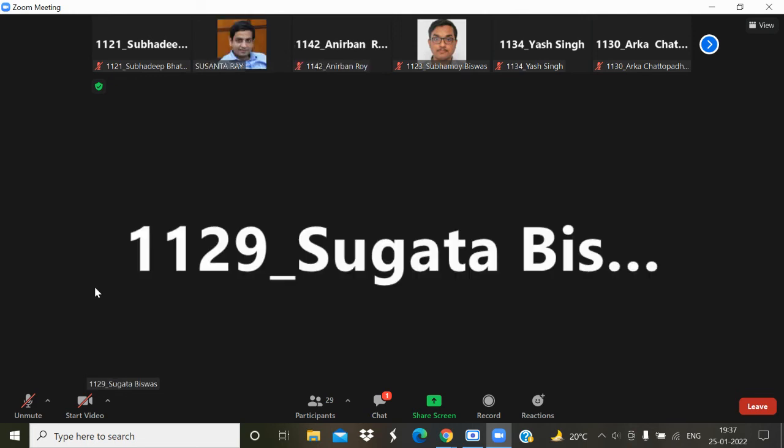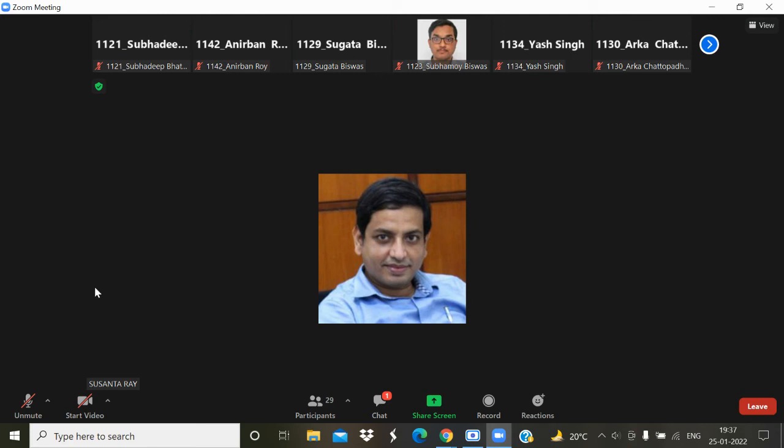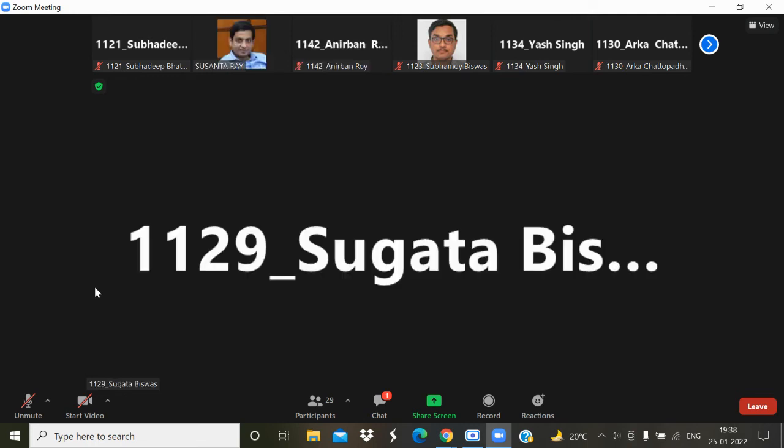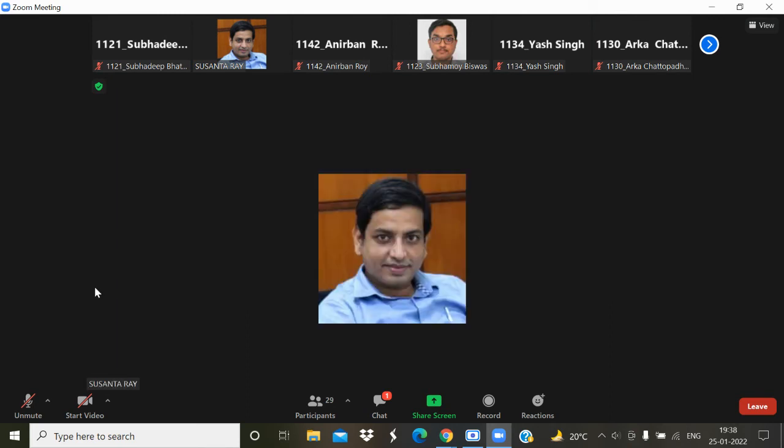Tau is basically pi D by P. So that will give you the L by D ratio. But the thing you have to assume is L by tau. That is the L by tau ratio, which you can assume 1 to 3 or 1 to 4, or 1.5. These are the values you can take.